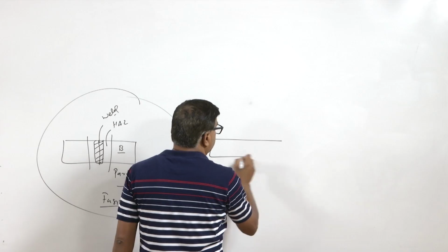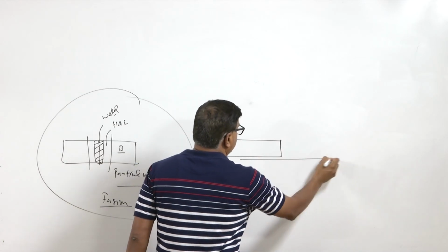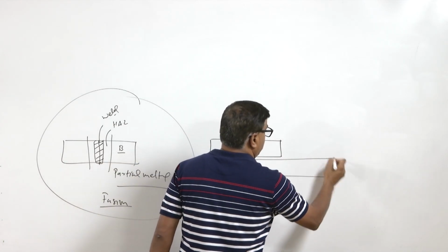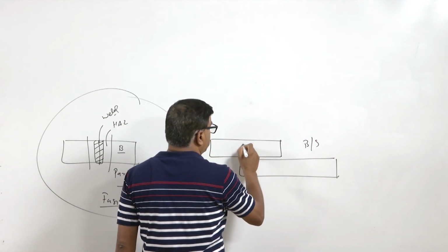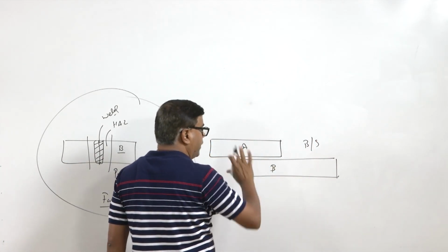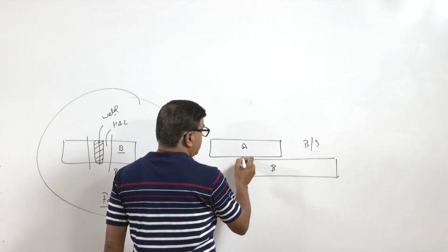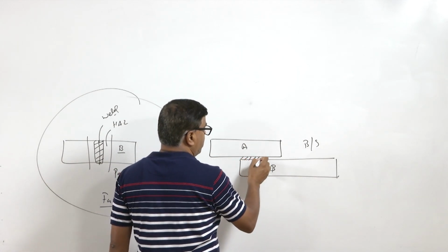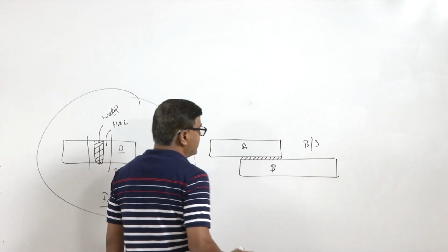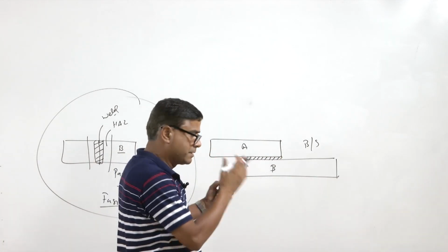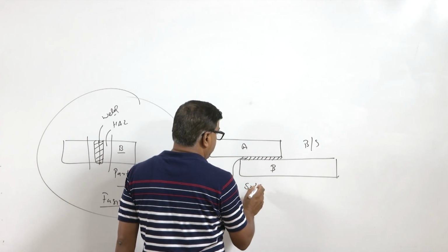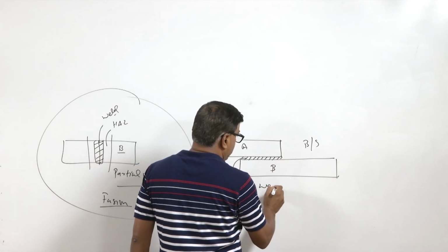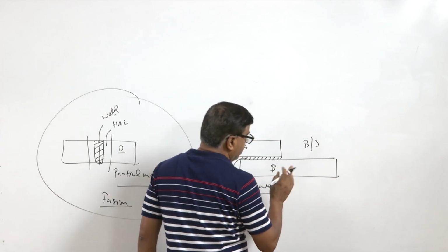The third category of process is the solid-liquid based process. Under this category we have brazing and soldering kind of processes, where both the components to be joined remain in the solid state. The only thing is that a low melting point metal is brought in between the faying surfaces, which after solidification gives the metallurgical continuity, but these joints do not become strong enough.